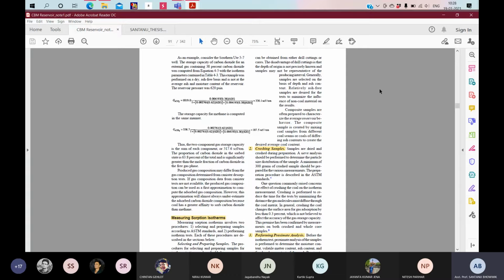Okay. Core sample versus powder sample, from where you will be collecting the sample, what the particular diameter or size range will be, and then what type of sample, dry or wet. Follow the standard accordingly and prepare the samples, because sometimes the preparation of the sample will take 2 or 3 days depending on the type and the volume of the sample. Okay, and when the sample has been prepared, now you are ready to do the testing.